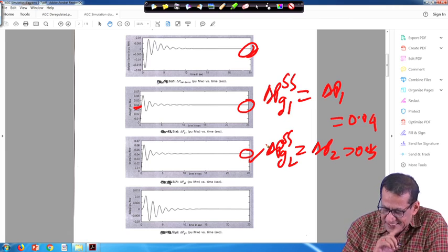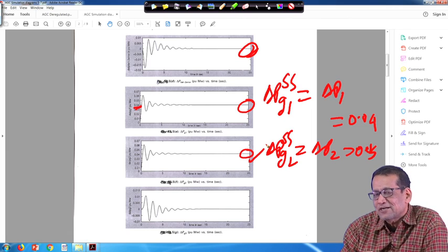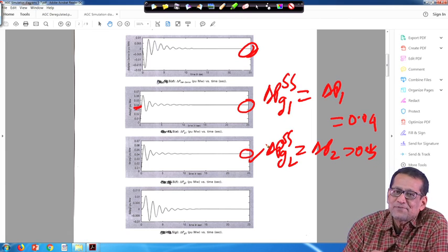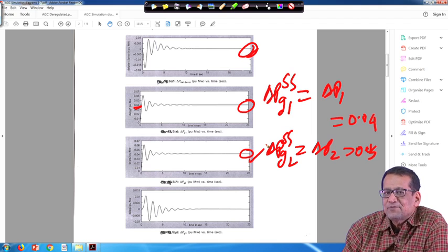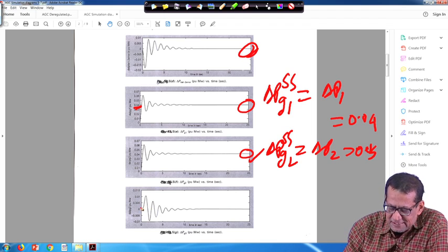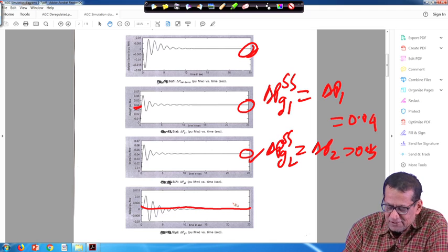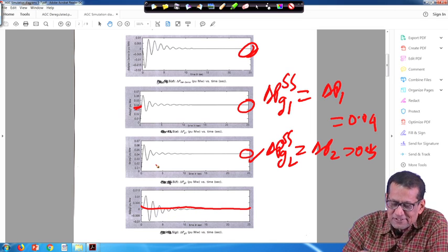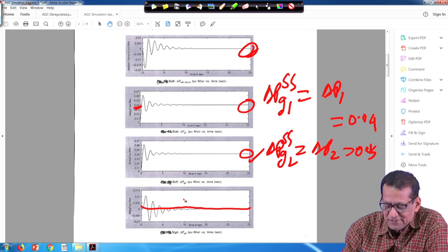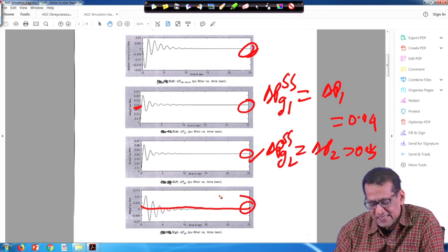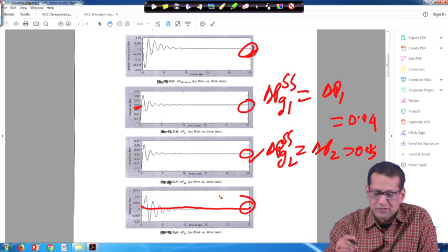But for delta P g 3 and delta P g 4, no DISCO has contracted with them, because other elements of the CPFs are 0 except CPF 11, CPF 12, CPF 21 and CPF 22. That is why the generation settles to 0, but during the transient some oscillations are there. Finally at steady state delta P g 3 is 0.